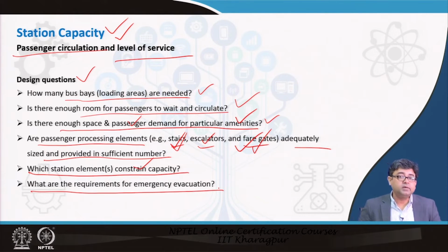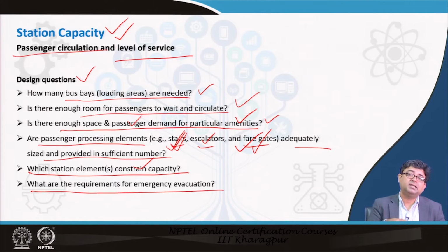That is something you always have to keep in mind, especially if you have a terminal or a station or a platform and an elaborate station. You need to have an emergency evacuation plan, because that is the time when the load is maximum, with the maximum number of people trying to get out of the station area. For example, your stairs should not be designed in such a manner that they would not be able to handle that capacity.